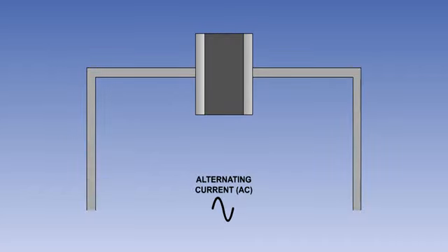Much of the electrical power used on aircraft is alternating current or AC. In AC systems, the polarity of the supply voltage changes cyclically. The change happens at a much greater rate than shown here. In fact, in aircraft AC systems, it changes 400 times every second.